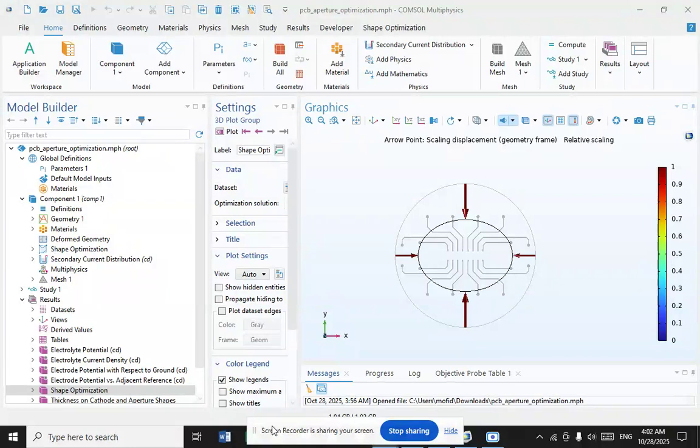of beamlet-based optimization. And in electroplating, the goal is to ensure a uniform deposition of metal by optimizing the shape and size of an aperture. The next is methodology. Software like COMSOL can simulate the process and use shape optimization to find the ideal aperture to minimize variations in thickness across the plate surface. The next one is application, often used to improve the plating process for components like printed circuit boards.